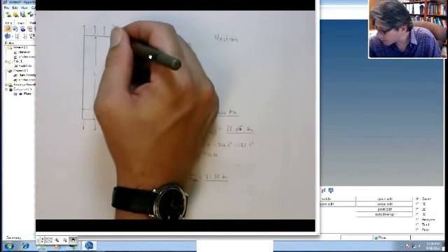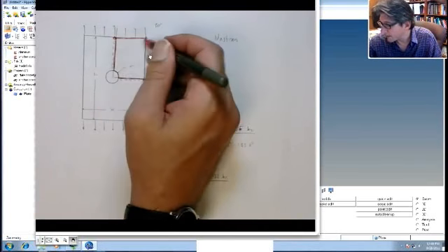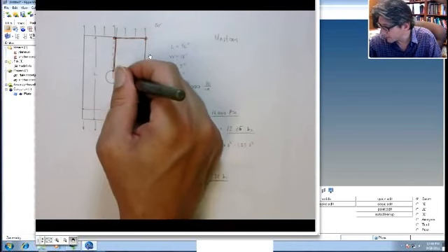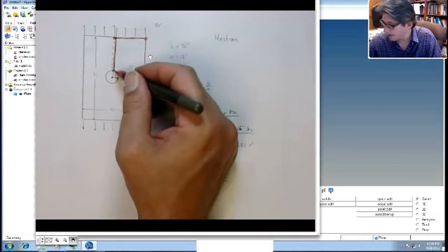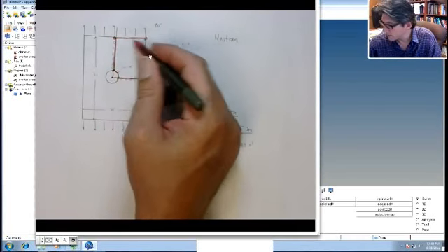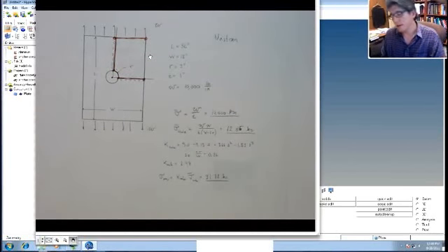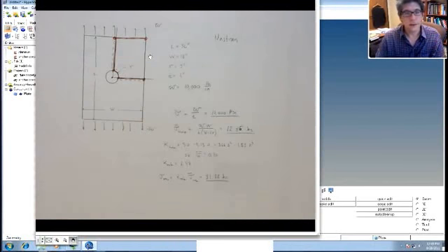And then to define the curves, you actually need to define the points. So for example, to draw a line from here to here, we need to define points here, and likewise for this edge. So I'm actually going to need to define some points as follows. So I'm going to define a center point. I need that to make this arc, and then we'll put points at all these sort of corners here like this, okay? Once I make the points, and actually Hypermesh calls them nodes, they're not necessarily the same nodes that go onto your mesh, then we'll connect the points using line and arc or circle, and then once we have the bounding curves, we'll mesh it, okay?